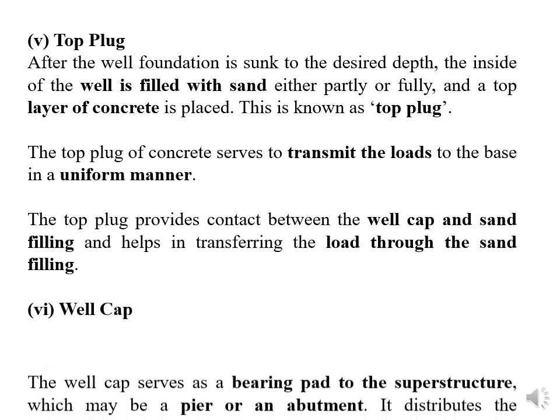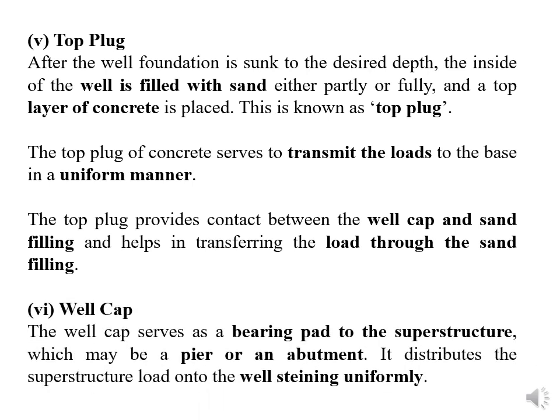Next is the well cap. The well cap serves as a bearing pad to the superstructure. Once you have constructed the top plug, then we have to go for the well cap. On the well cap, you have to start the construction of the pier, right? On the pier, then you have to go for the girder, or you can construct the railway. You can lay down the railway lines, or you can also go for the road construction.